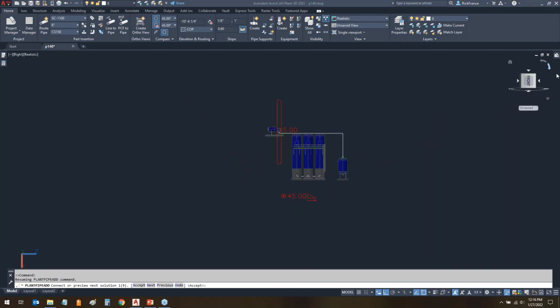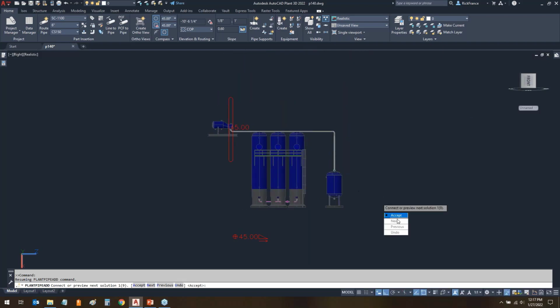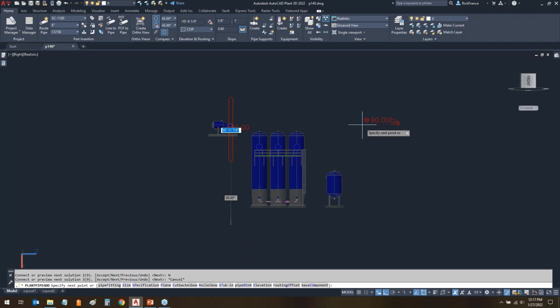I'm going to have to move this down a little bit, this part of the screen for the webinar. Okay, out of the way of that. But you can see here, that's not sloped at all. Nowhere at all. And I could go through every single one of these. None of them is going to slope the pipe. So rule number one of things to remember, auto route does not do slope pipe. It's impossible for it. I mean, well, it's not impossible. It's just it doesn't do it out of the box. So the auto route does not help me.